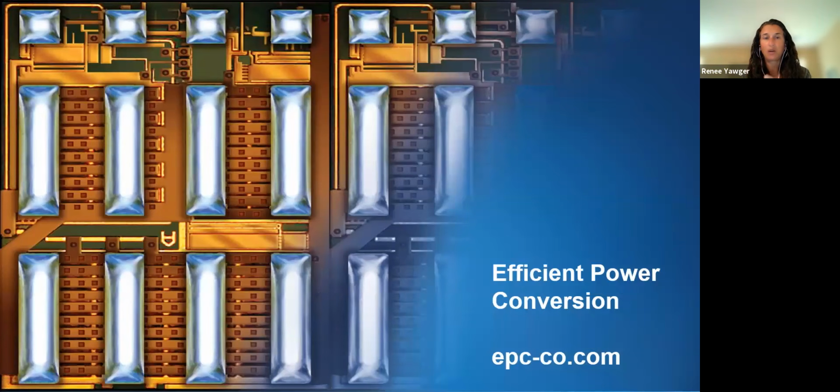The first one was, how do the vias from different nodes, especially switching one, affect EMI? We found in many cases that we use internal switch node planes to reduce the resistance of the switch node. So I see your point, which is what happens when you have very sharp rising edges and you spread that out further into more planes.